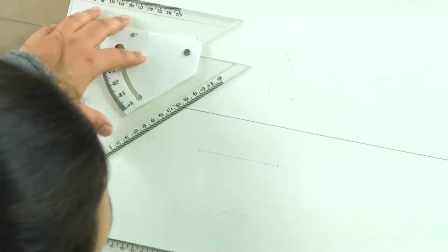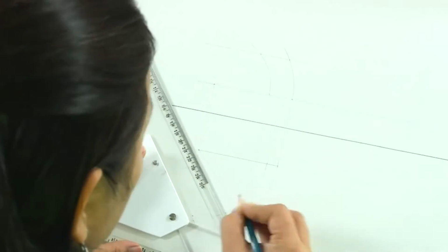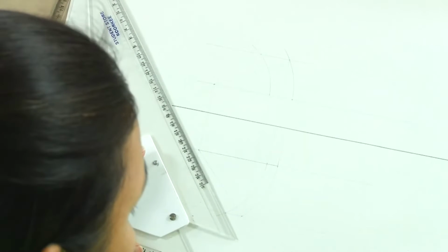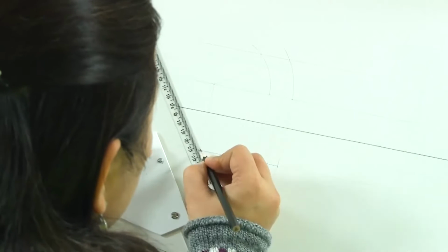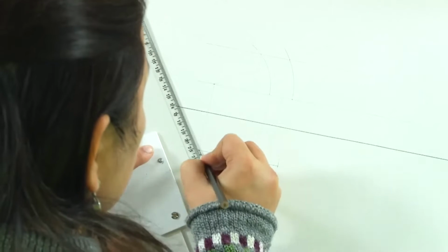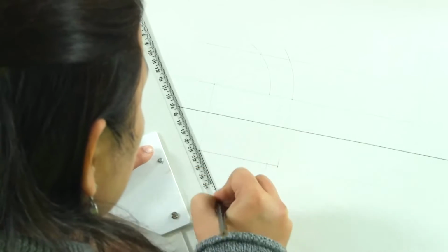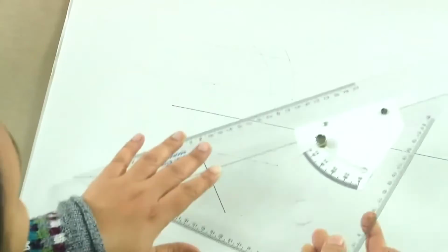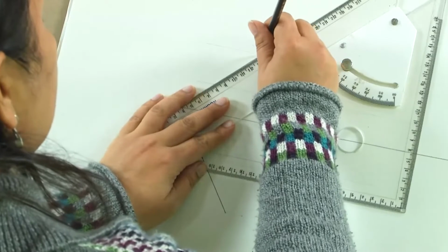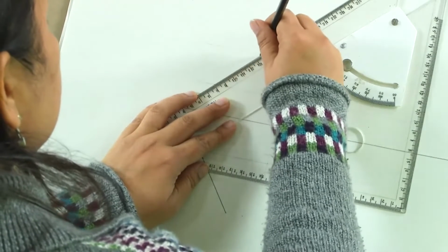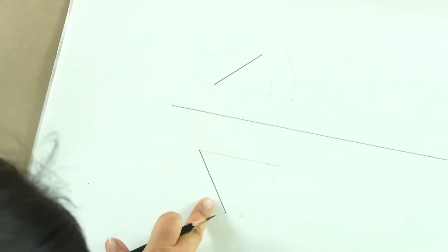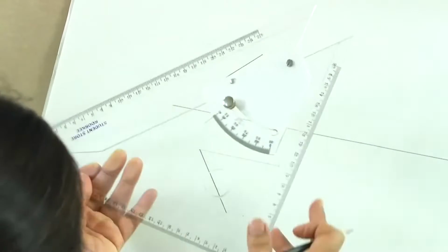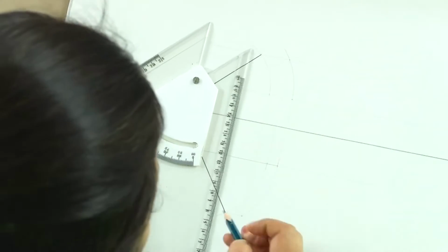And so the final line that we get here as a result, this line, this is the top view, and this line here is the front view. So this is the top view, this is the front view, and if you can see clearly, I'll slightly darken the projections for you.